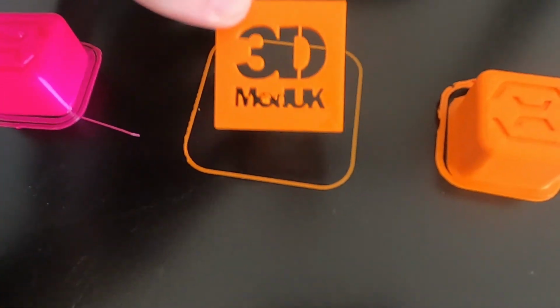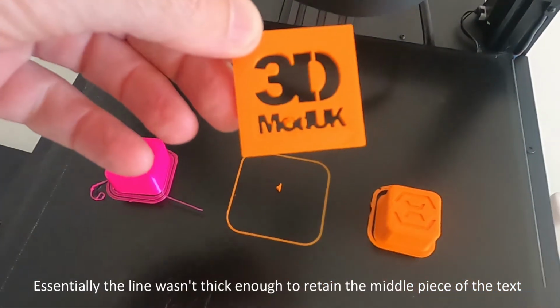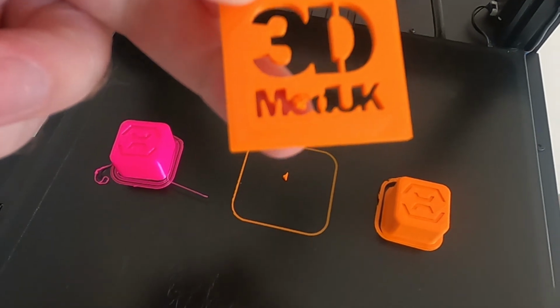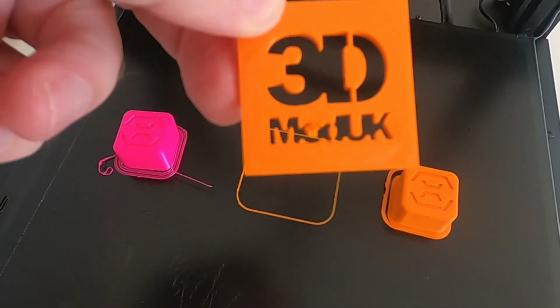So I've missed the middle of the 3 and the D, so that's why that's stuck on the bed. And also because I'd made the O and the D much smaller supports, we can see that it's kind of blended with the top of the O and missing the bottom of the O, but the D's not too bad.